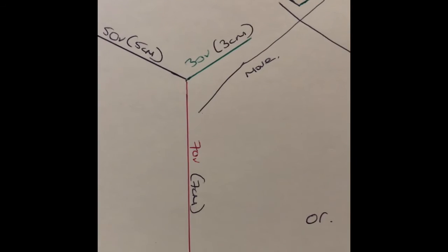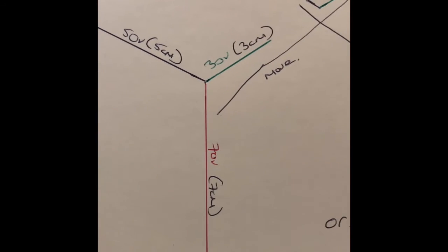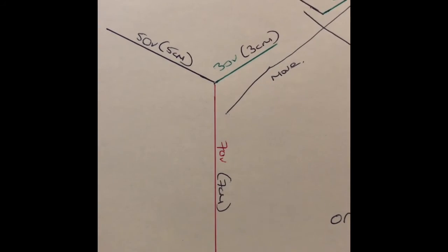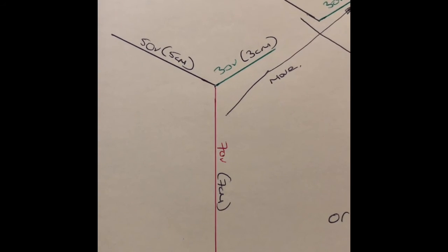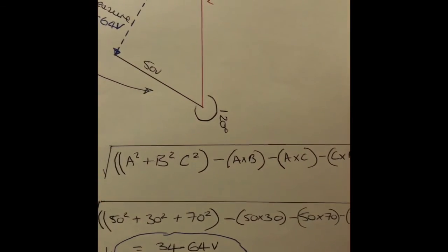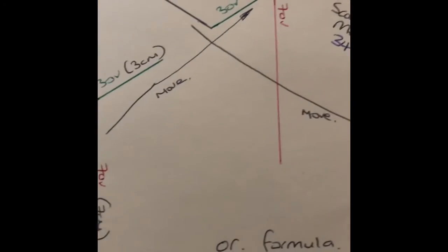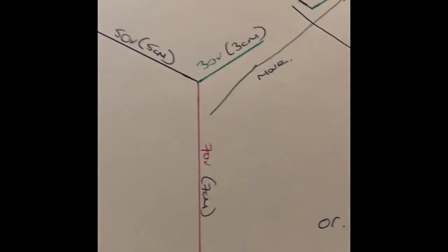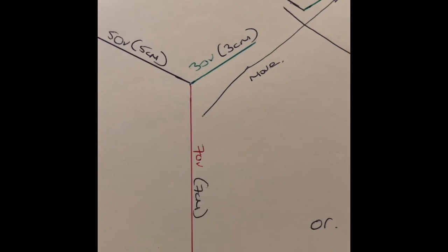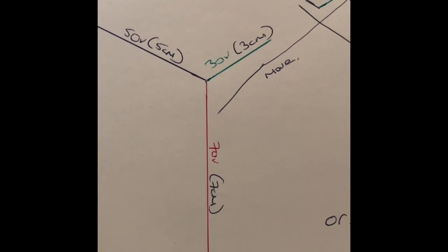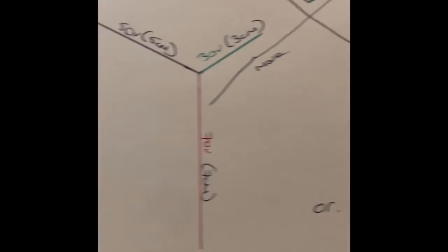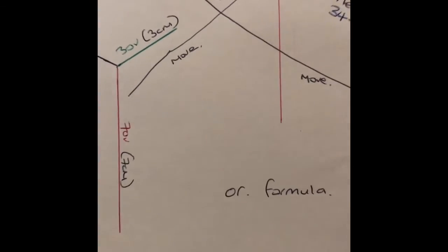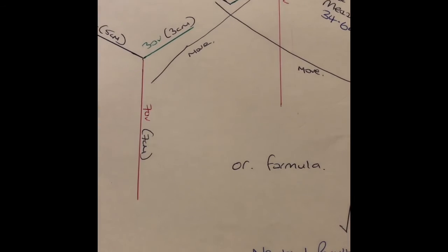From this though, we know straight away that it's an unbalanced system, but we need to calculate again how unbalanced this is and what's going on in here. So we can use a nice big formula, or we can use the drawing method. The second method, rather than using a protractor, as long as this is drawn out for us, we can basically just move some of these lines, and hopefully you can again see from here.